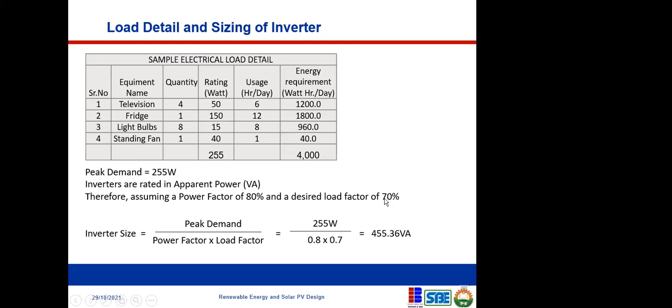That's your desired load factor. So you have a tolerance of 30%. All of those things have to come to bear if you want to determine the size of inverter that will carry this load, and give you this tolerance of 70% load factor and a power factor of 80%.